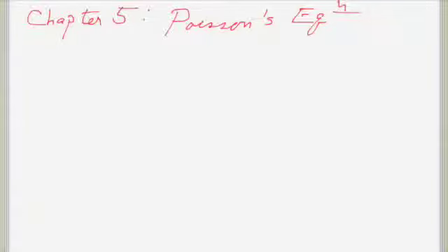Okay, on to chapter 5. Okay, so Poisson's equation. When you're doing device modeling, so far we've just talked about solving Schrodinger's equation with non-equilibrium Green's functions, and we calculate two things: current from transmission, and charge. We've developed these algorithms to get charge, but the only reason you're getting charge is so you can calculate a new potential through Poisson's equation.